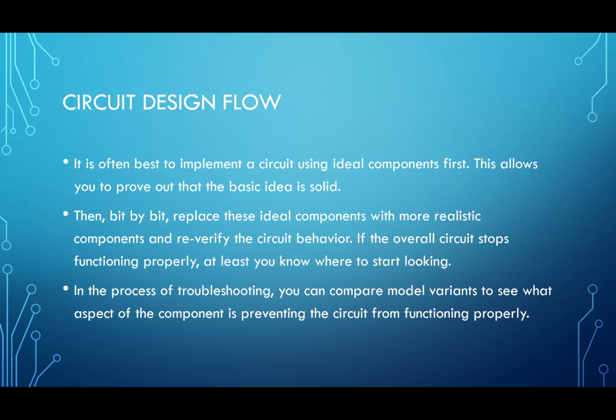So within the flow of circuit design, it's often best to implement a circuit using ideal components first, because that allows you to prove out that the basic idea is sound. Then bit by bit, you can replace those ideal components with more realistic components, like we did with that op amp, to verify the circuit behavior in the presence of these non-idealities, like non-infinite gain bandwidth product, or non-zero output impedance, or whatever.